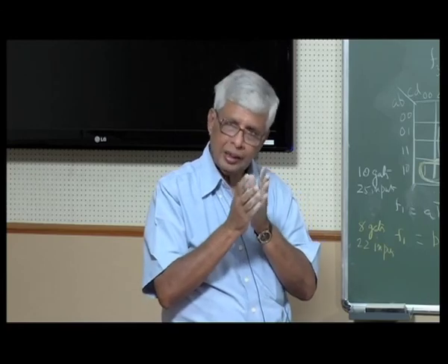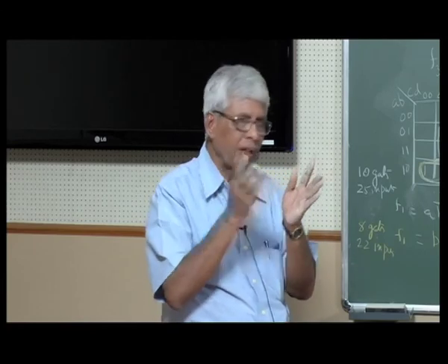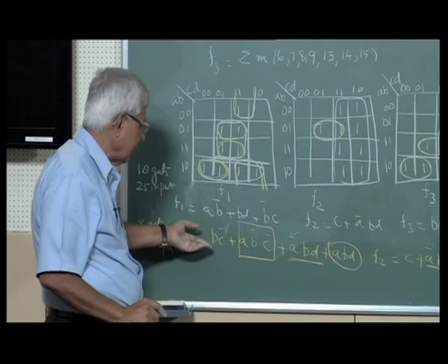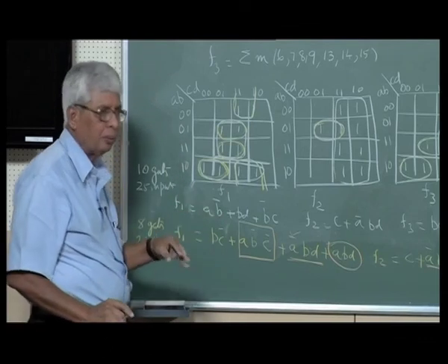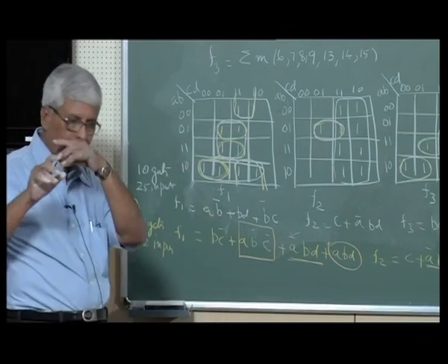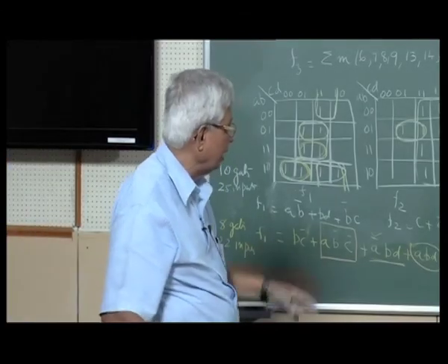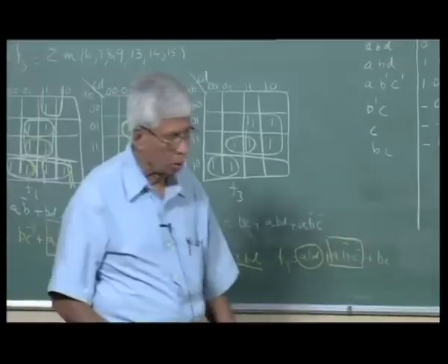If you can do it, fine, then there will be F1, F2, F3 as I had done here. But if you do this, I can reduce the number of product terms, thereby making the size smaller. So, what is the size of this? As I said, size, you do not simply say inputs times outputs. The size is now, you have to also include the number of product terms.